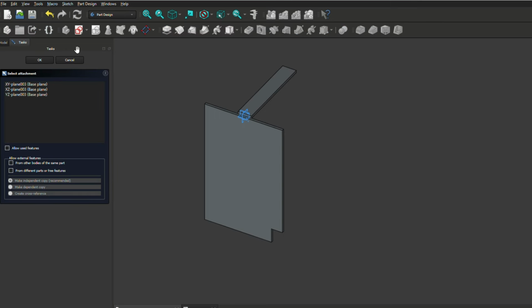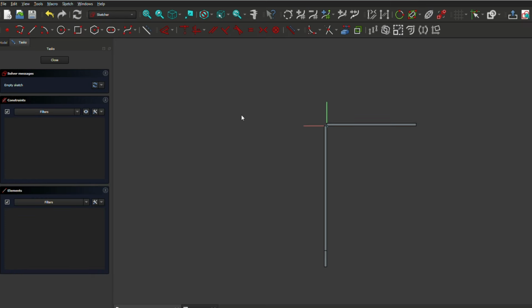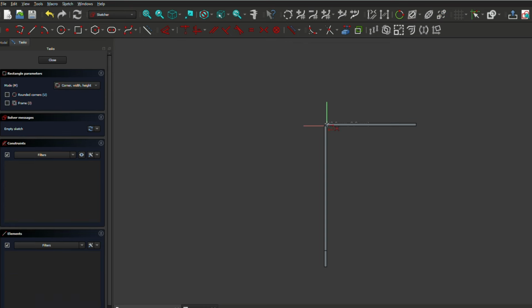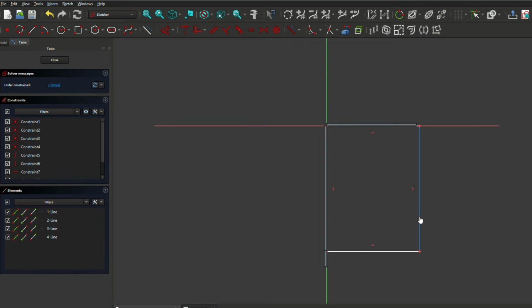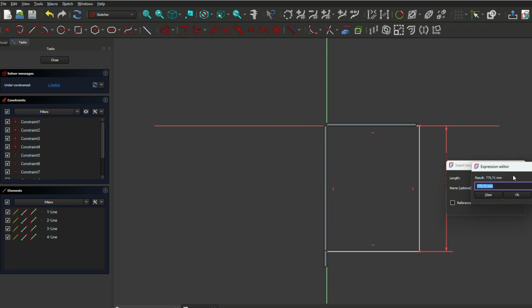In the door body, create a new sketch and select the YZ plane to position the door on a side plane. Draw a rectangle from the YZ center point and enter. Select the door height line, then choose the Dimension tool and press Enter. Click the small expression icon in the length cell, and then enter the Dimension spreadsheet.